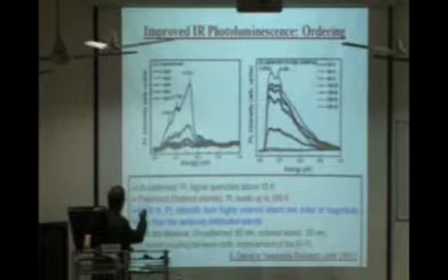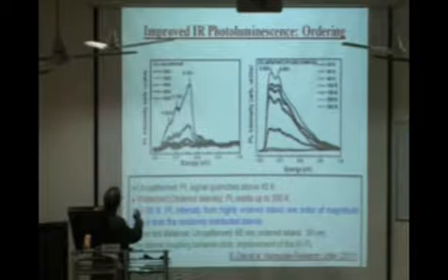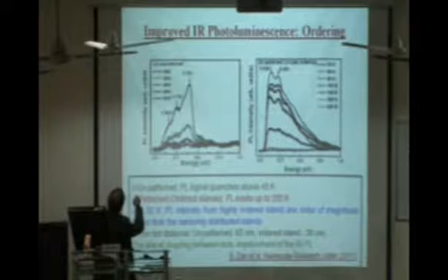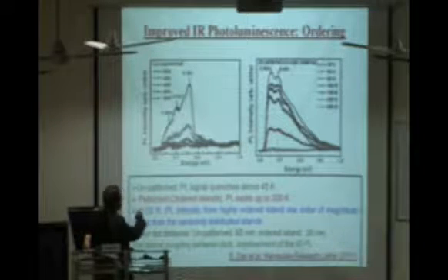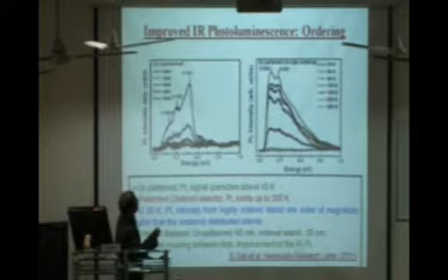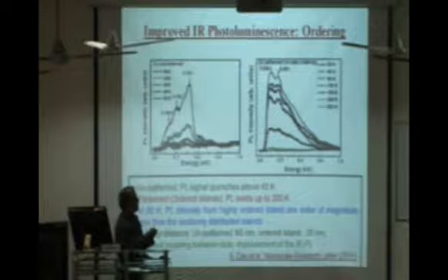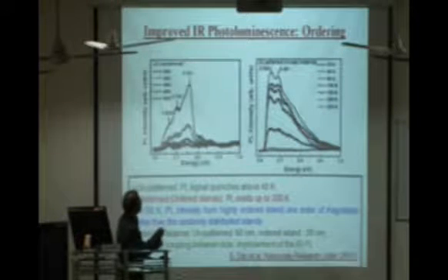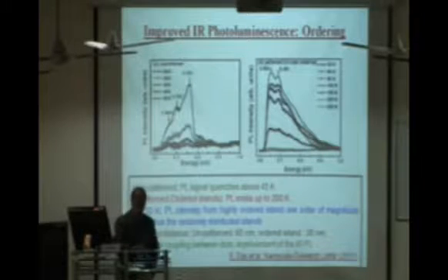As soon as you do this, from the same substrate, if I take a luminescence in an unpatterned substrate, as I said, it quenches at 50K. So after 50K there is no emission. But as soon as you get periodically ordered quantum dots, the luminescence exists well up to 200K. It only quenches around 250K. So that is a very nice experiment.